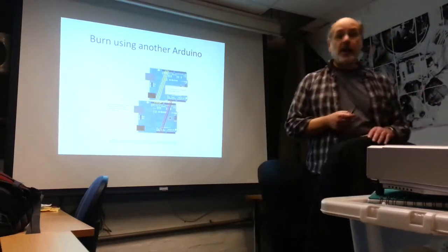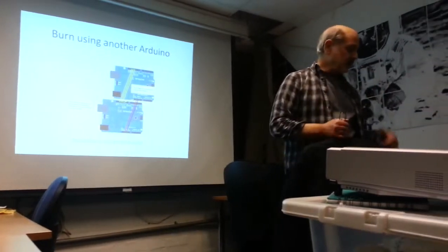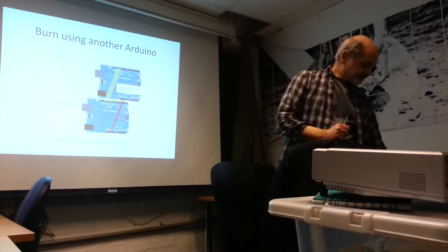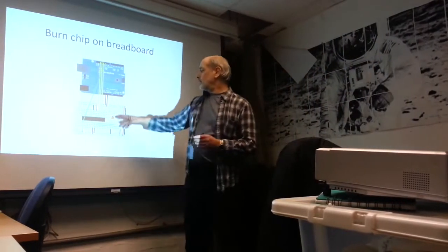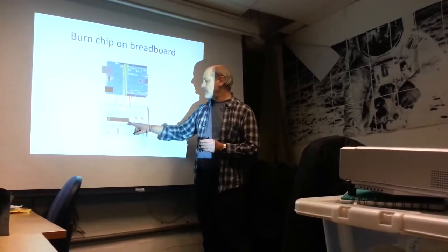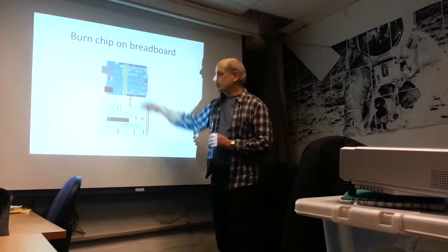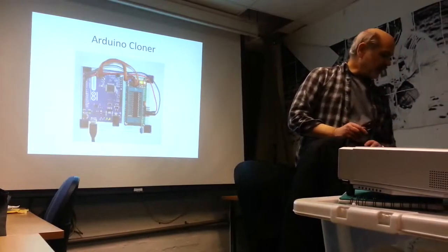And the IDE has, under the Tools menu, an option to burn the bootloader, and you select the kind of programmer that you have. Typically, you would burn a bootloader into a raw chip that perhaps you're building into an embedded solution. And as I say, you can use a standard Arduino if you don't actually have a programmer.